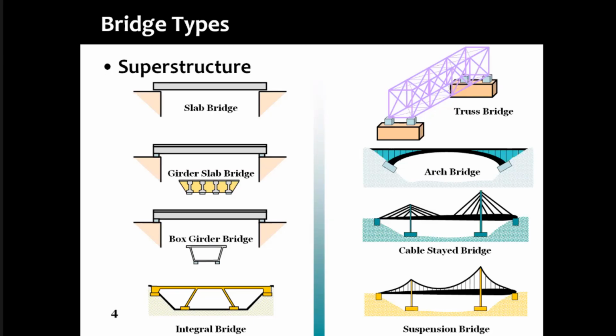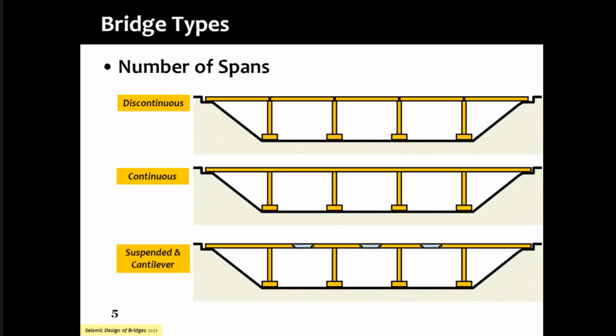So once again, in a bridge, damage will be in the vertical member and not in the horizontal member, because we cannot damage the horizontal member. In a building, the damage will be forced in the horizontal member because we cannot afford the luxury of damaging the vertical member in a building. We talked about discontinuous bridges requiring a lot of bookkeeping, and continuous bridges requiring relatively less bookkeeping. So we would like to see as many continuous bridges as possible in strong seismic areas.